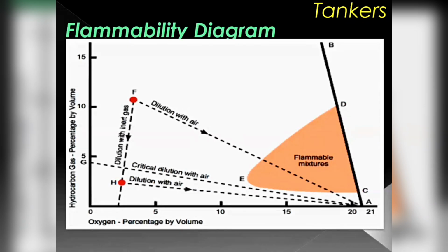Sir, some cargoes eat up oxygen and then produce lots of hydrocarbon gas. So while carrying those kinds of cargoes, if we don't inert, I think it's still kind of safe. You cannot allow the fresh air to go in. Even if the pressure has gone negative, you should never at any stage allow fresh air to go inside the tank. Yes, you are right. Some cargoes are like that, they eat up all the atmosphere.